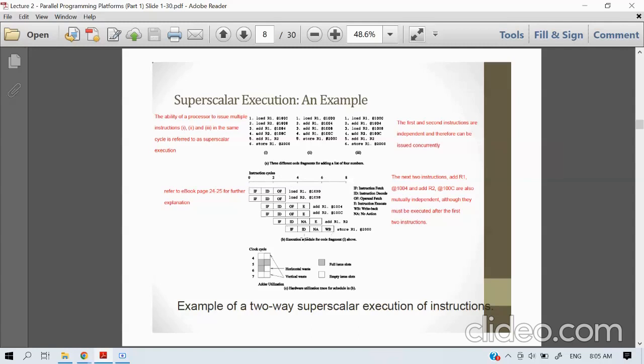From the execution schedule, we can transform to C, where we want to look at whether the hardware is really being utilized or not. Taking time number 4, there is a waste here, where there is no instruction being executed during time 4.